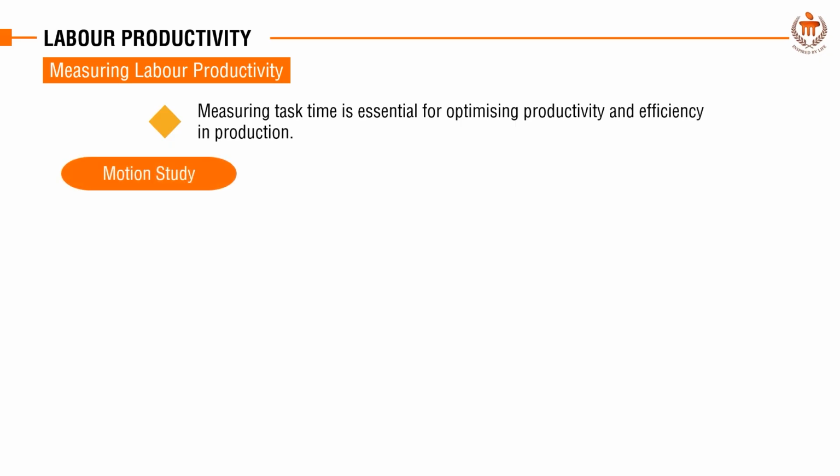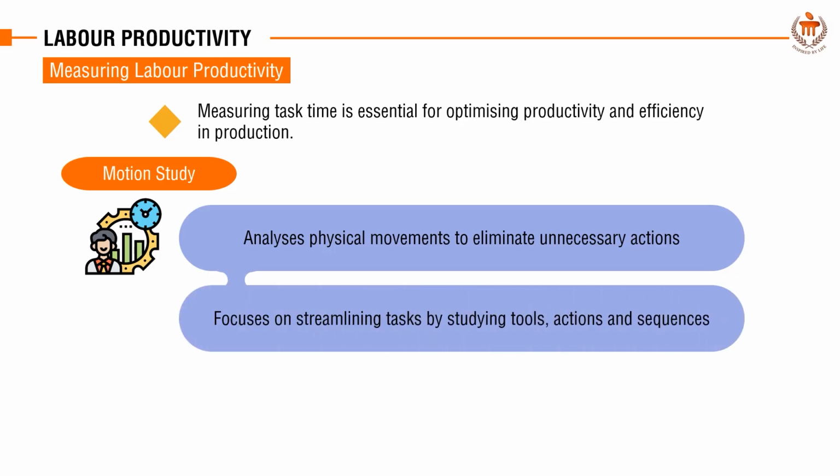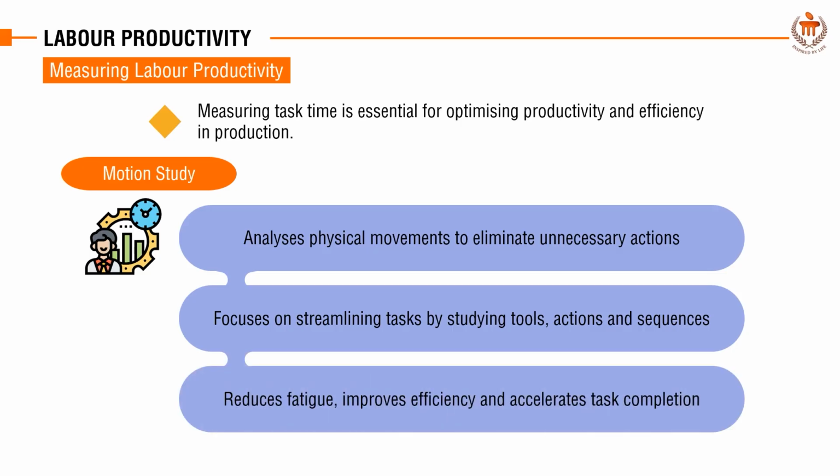Motion study. Motion study is a tool used to analyze the physical movements required to perform a task with the aim of eliminating unnecessary motions and streamlining the process. The objective is to identify the most efficient method for carrying out a task by studying the worker's physical movements, tools, and sequence of actions. By eliminating wasteful or repetitive motions, motion study helps improve efficiency, reduce worker fatigue, and accelerate task completion.